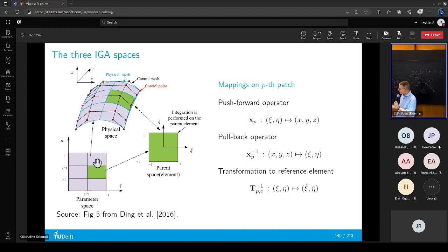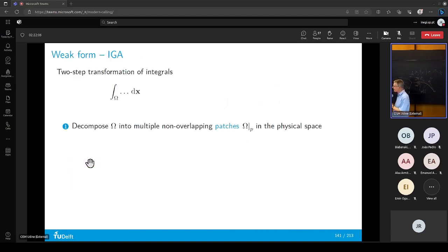A little bit oversimplifying. And then the weighted quadrature kind of sits locally here and integrates over all the elements in which this basis function is not 0 at the same time. But it has some other difficulties. It doesn't give, for example, symmetric mass matrices, because it's constructed like that.